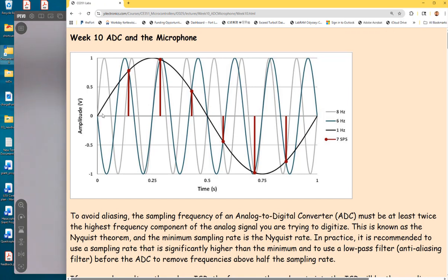You can see a sine wave. For example, these red points are the points we sampled. If you ignore all these different sine waves with different frequencies, just imagine that there are only 6 points being sampled, and then you plug all the numbers in Excel or Python and let the software plot it, and there are multiple options. So this big sine wave is not the only option. It might be plotted in different ways with different frequencies. So in that case, you won't be able to recover your actual signal's frequency, and that's a big problem.